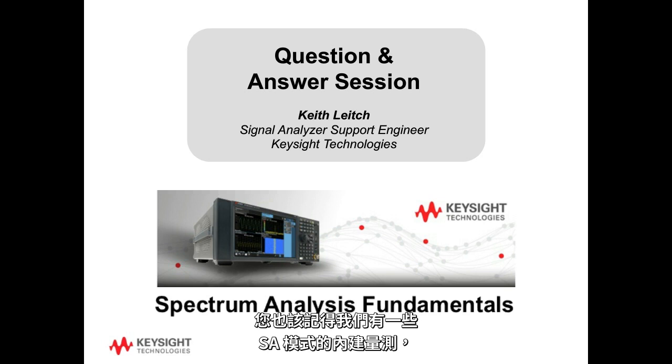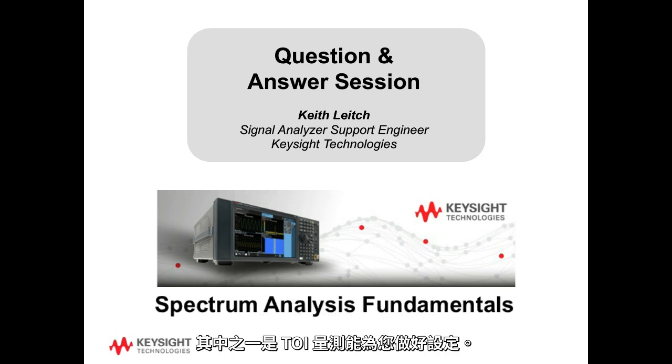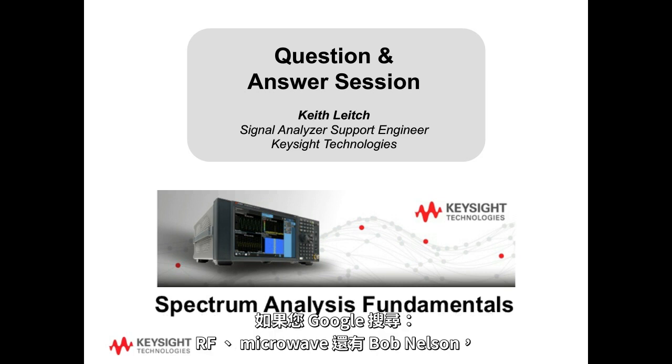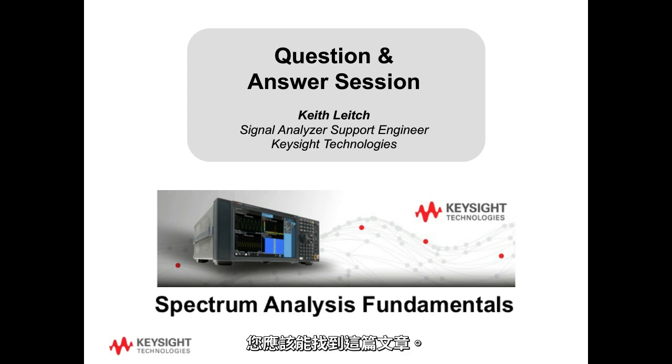And then you have to remember, we have some built-in measurements in the SA mode, and one of the built-in measurements is a TOI measurement that takes care of the settings for you. And then there is an awesome article that Bob Nelson from Keysight wrote for RF and Microwave that goes into TOI measurements. So if you do a Google search for RF and Microwave Bob Nelson, you should be able to find the article.